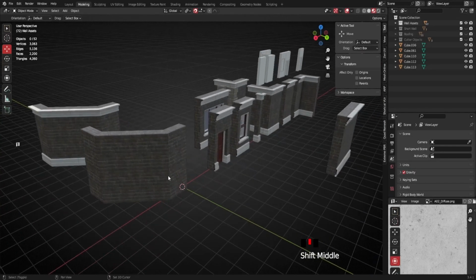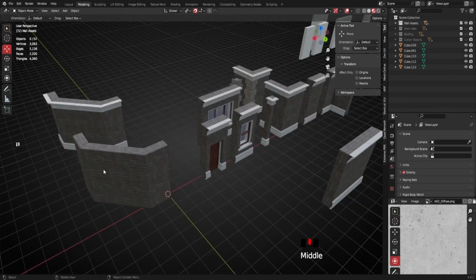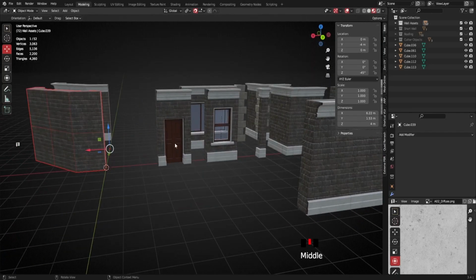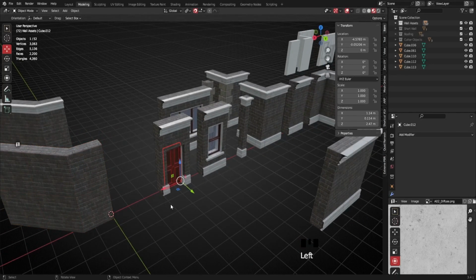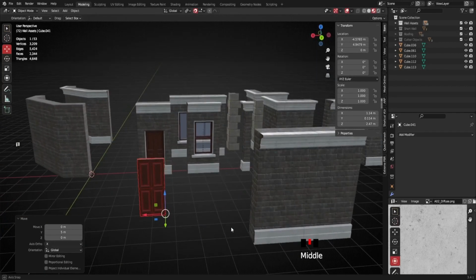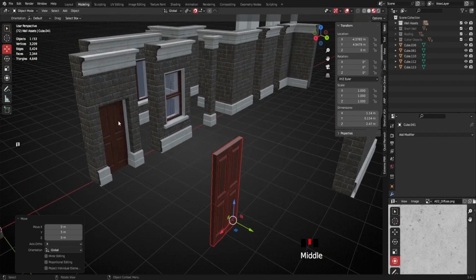So now what I'm going to do is I want to cut the double doors into this blank piece here. To do that, I need a door. I'm just going to grab him. I'll borrow this one, Control D to duplicate, and I'll just pull him forward. And you can see I've actually got a kind of dotted line here, so that means this is parented to the wall,